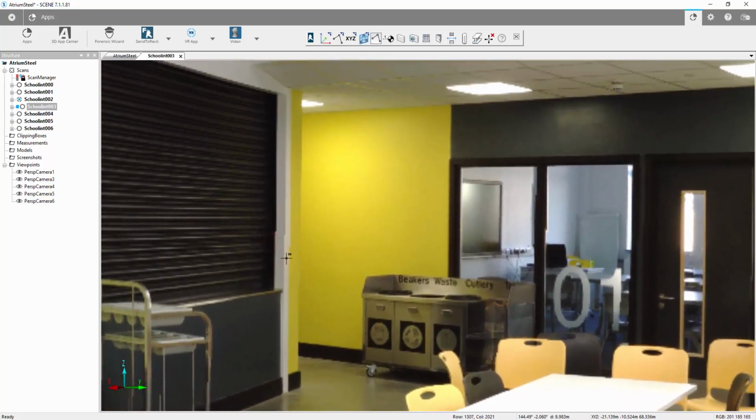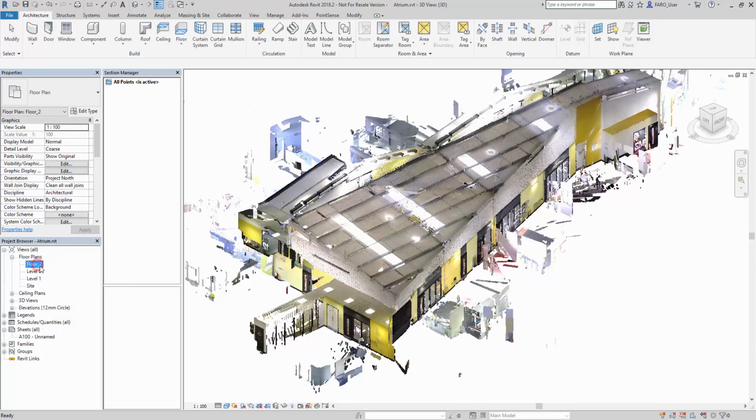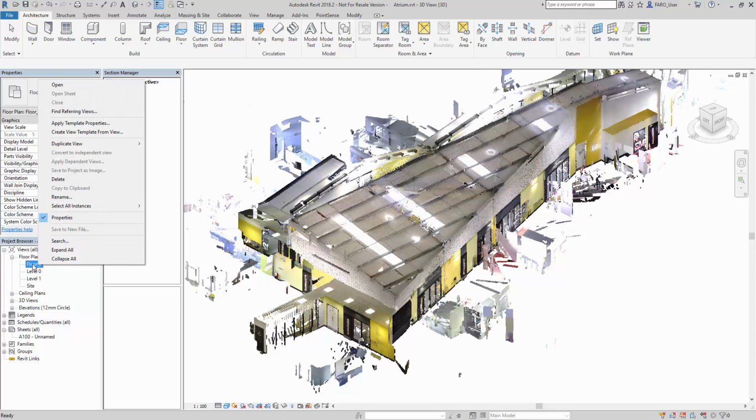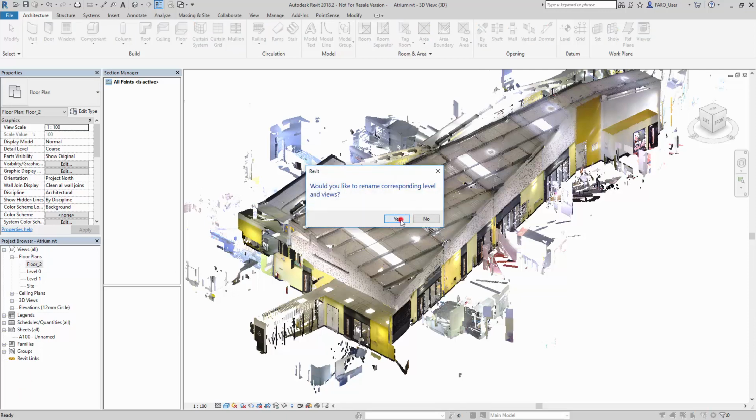at this wall, I can activate a command inside the toolbar, such as the level command, and I can take a level on the floor here. What will happen in my neighbouring Revit project is that we'll send that level into Revit. So you can see here now we have this floor 2. If I rename that as ground, and we open that one up, you can see we've cut that level at that plane.